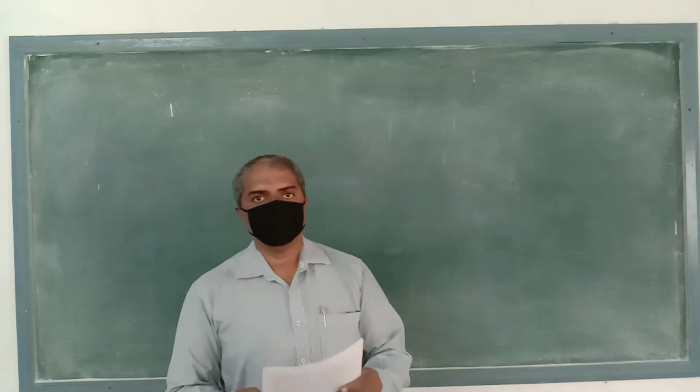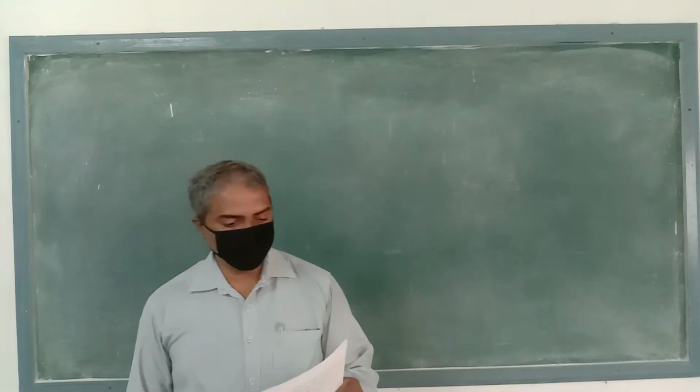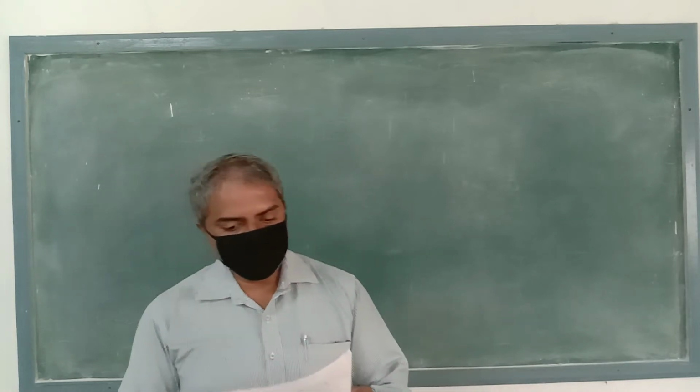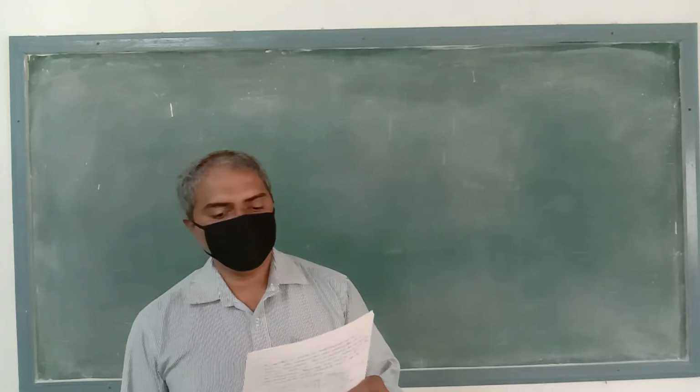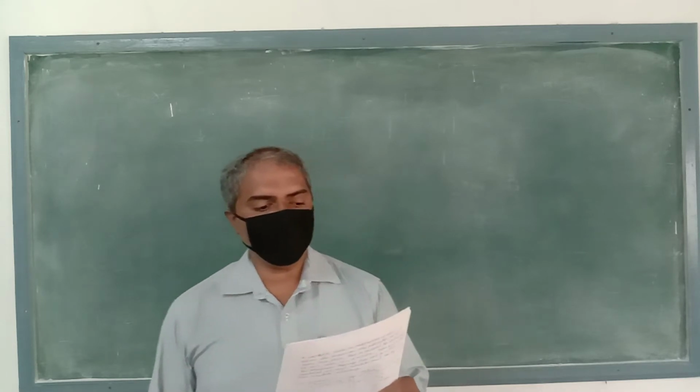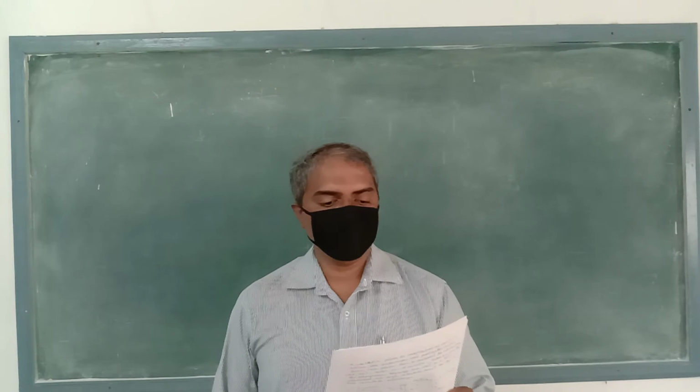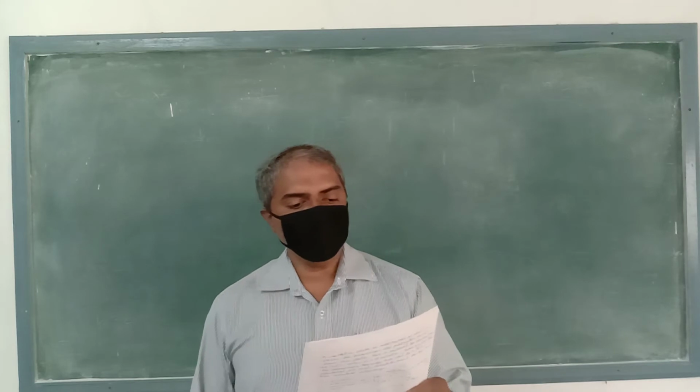Good morning, students. Note down the problem related with the fin. Write down: an electric motor is to be connected by a horizontal steel shaft whose conductivity K is equal to 42.56 watt per meter Kelvin, 25 mm in diameter, to an impeller of a pump circulating liquid metal at a temperature of 540 degrees Celsius.